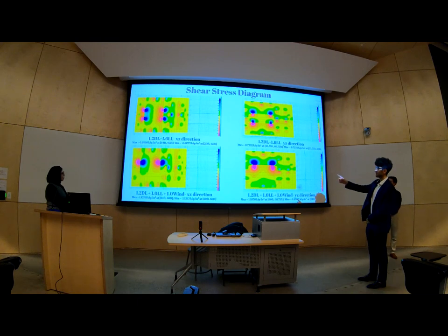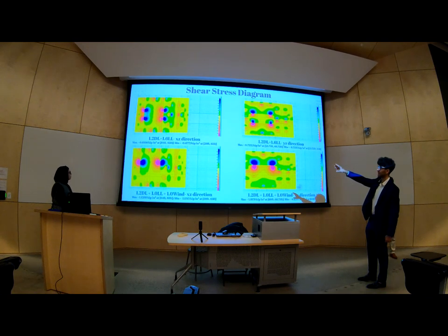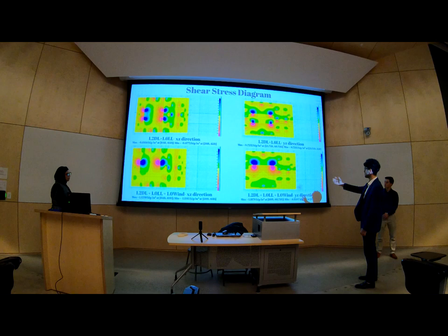So in the S13 direction, which is the XZ direction, we had a maximum shear stress of 0.6166 kips per inches squared. Inside the brackets are just the coordinates, which you can clearly see by the colors is where the core sits, as well as the minimum, which is a negative 0.6772 kips per inches squared, also right next to it, but on the other side in the core.